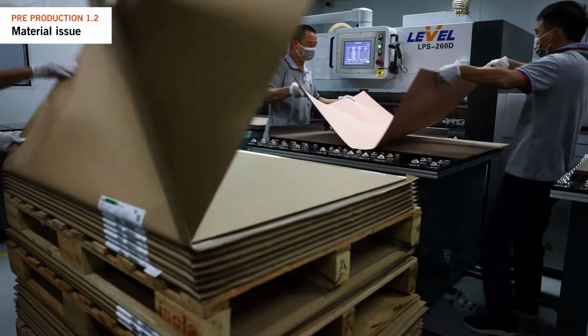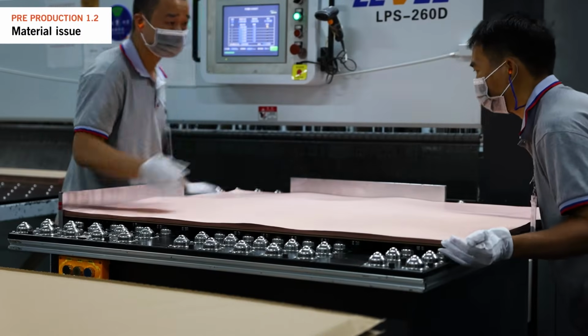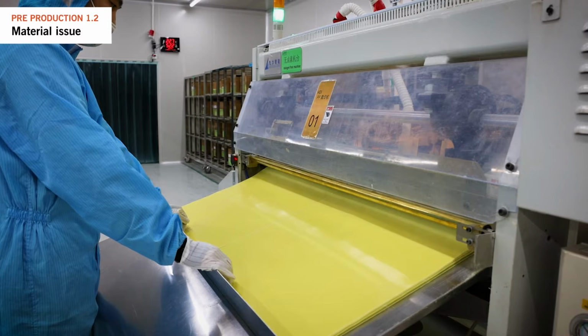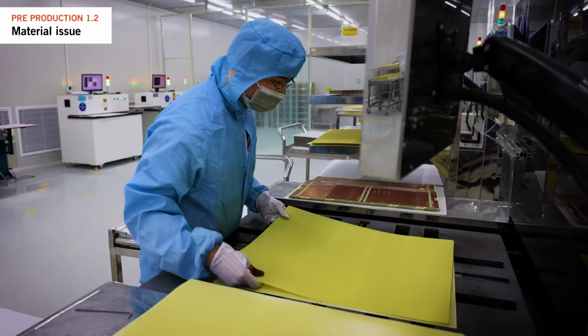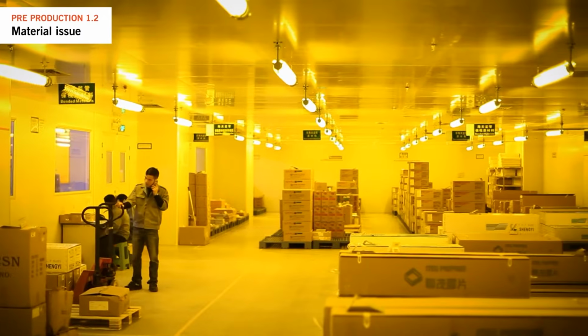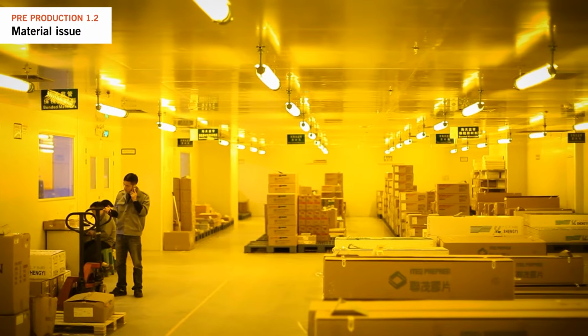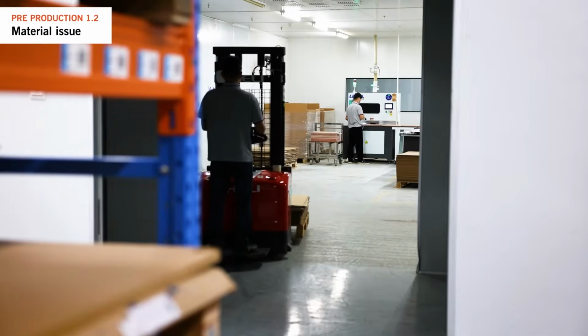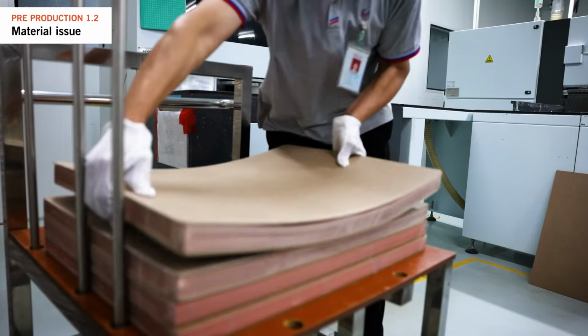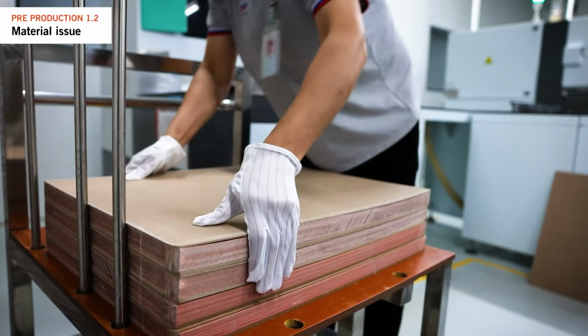Since these cores are already fully cured, they can be stored under normal storage conditions. Another type of material is prepreg. It's similar to the cores, but without copper foil. Since prepreg isn't fully cured, it must be stored in controlled temperature and humidity conditions and has a maximum shelf life of 6 months. It's crucial to follow a strict first in, first out approach when using both materials.